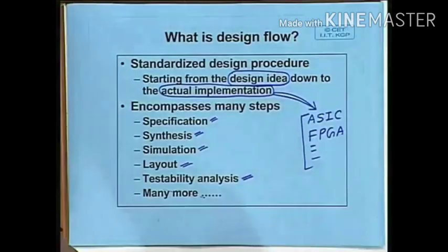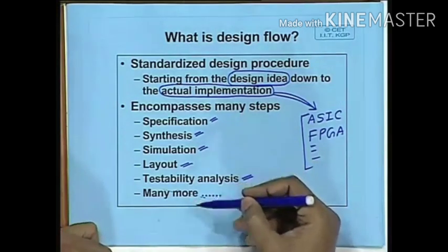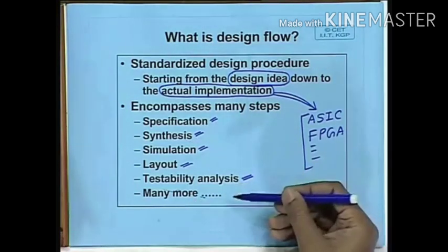Now here I have just told you that you today have chips which can house millions of transistors, but externally you can have only a few hundred pins available to you. So just using those few hundred pins, how do you test those million components inside? There has to be some special design effort that has to go in during the synthesis process itself, so that during testing it becomes easier for the test engineer to test the chip. There are a number of techniques called design for testability, built-in self-test. These are the things we'll be discussing.